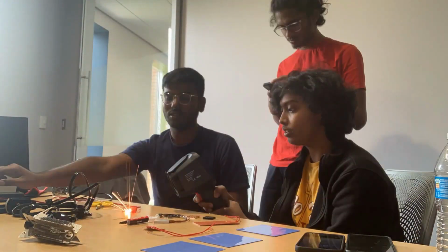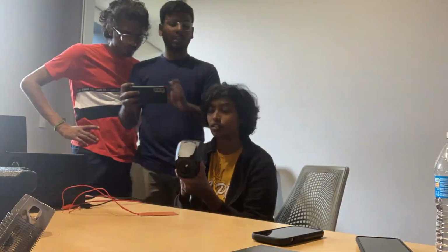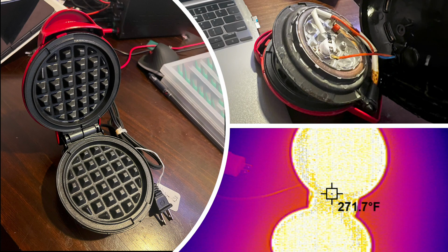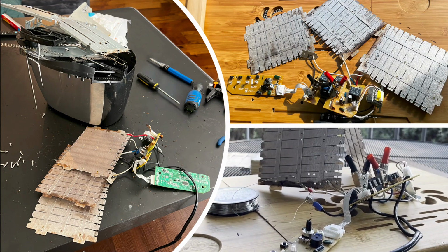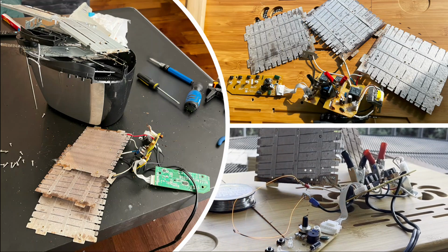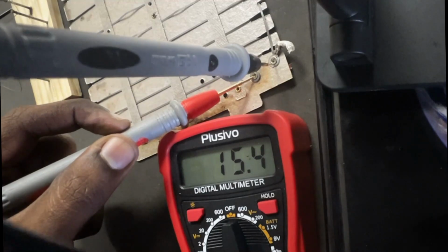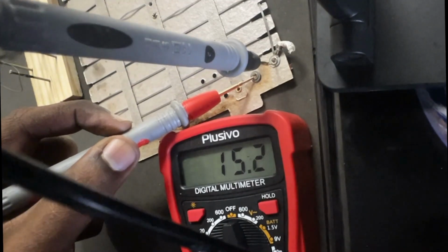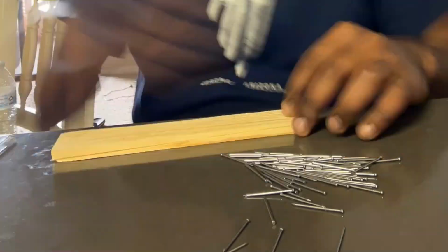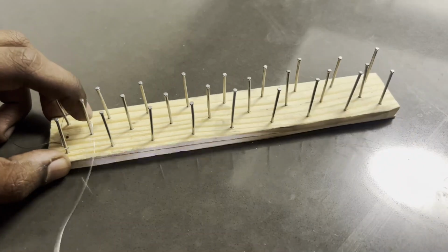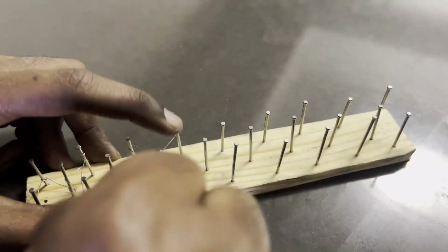We started brainstorming and finally decided to start by breaking open some appliances that use heating elements. After running through a couple of appliances, we found the ideal circuit for our application in a toaster. After some more discussions, we got to work. The nichrome tape's resistance attached to one of the mica sheets came out to be around 15 ohms. So we started to test the model out using different nichrome wire patterns and different resistance values, which is directly proportional to the length of the wire.